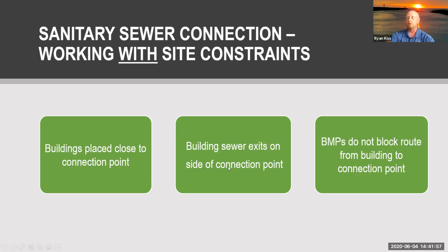For the same reason, it gives us flexibility of setting the best finished floor elevation that we can to keep the cost down. And then if possible, we don't want to place buildings or stormwater management facilities in locations that are really going to cut off access and make you really have to go a long way out of your way with your sewer runs to try to wrap around them, because oftentimes by adding that extra length, it makes connecting in either not feasible or it causes us to have to elevate finished floors on the upstream side of things way more than we would want to. So these would be the items that we would want if we were looking to work with that constraint.